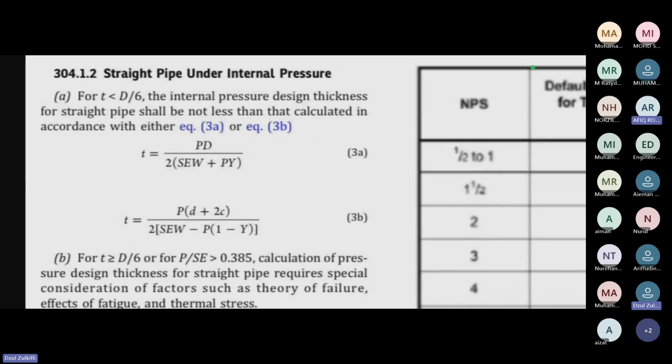So that is the reason why typically, if you have a very big stiffener ring, or a very big weldment that is welded to a different shape, for example cone to shell or something like that, FFS cannot be done. So sorry for the long answer. Short answer is yes, typically you can, but you need to evaluate the size of the stiffener ring, which usually should be okay, because the stiffener ring is also usually corroded, so usually the size is okay.